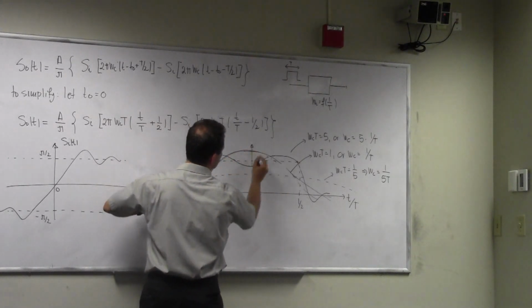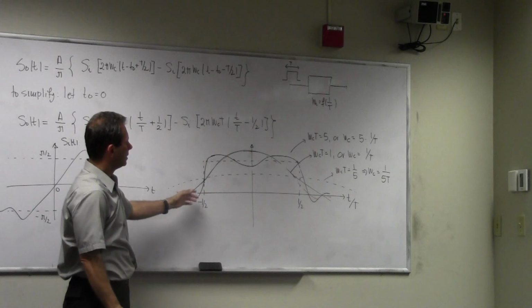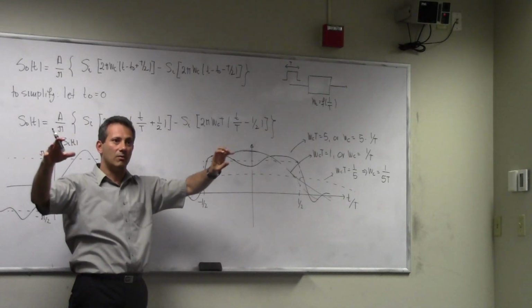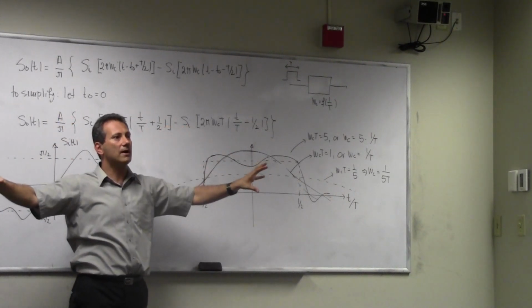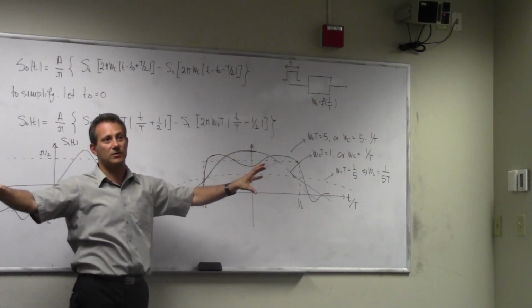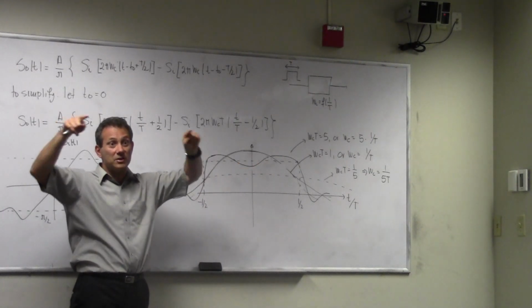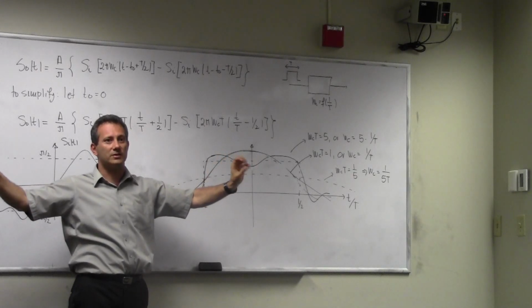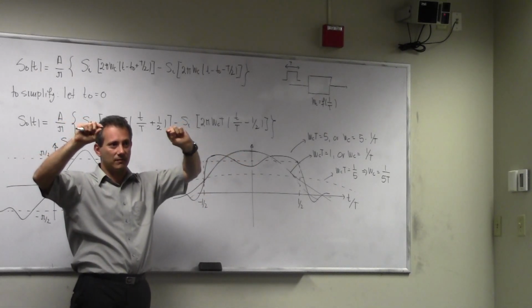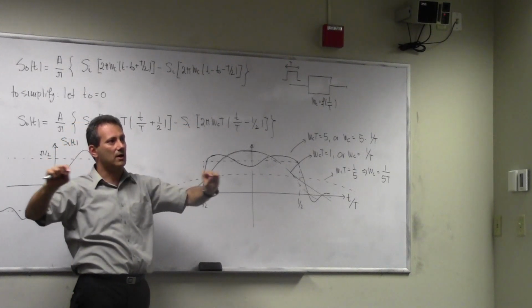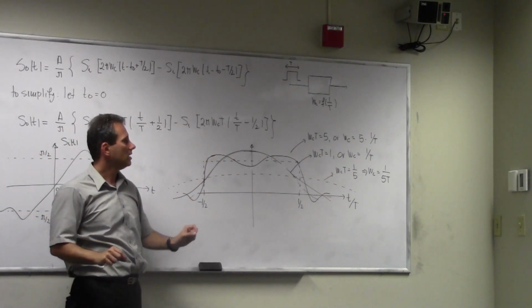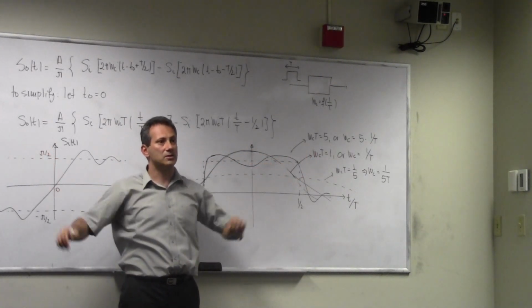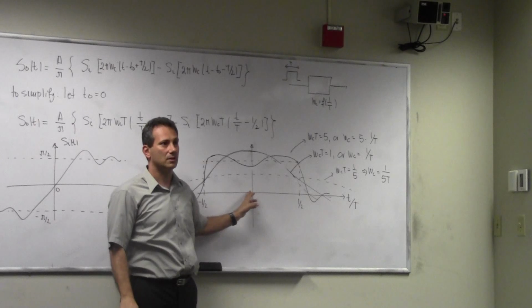So this is for WC equal to 1. So your pulse is not square anymore. It becomes round. Why? Because you cut out all the high frequencies that made it square in the first place. Remember, those sharp edges in your signal are made out of high frequency components. They're the fine building blocks that allow you to create those edges. If your filter has a bandwidth that cuts off those edges, then your signal becomes round.